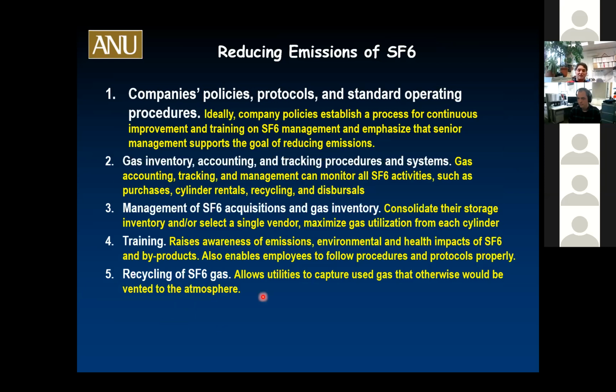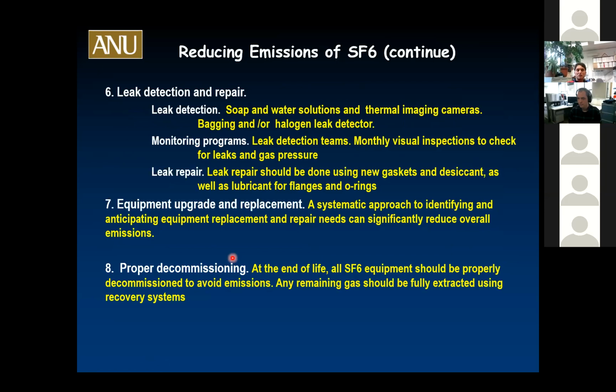So, recycling SF6 gas. We need utilities to capture used gas in any quantity, and then we don't allow these gases to go to atmosphere. So we can continue. Certainly leak detection and repair is a big attribute of SF6 work, like leak detection with soap and bagging, or using halogen leak detectors. Monitoring programs, like leak detection teams. So we do this on a regular basis, with a visual inspection to check for any leaks and also gas pressure in components, in storage vessels, in main vessels, and so on.